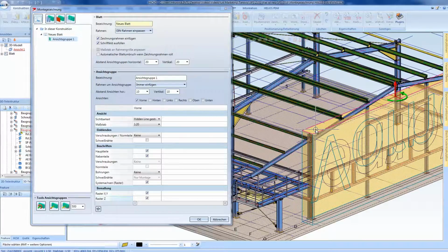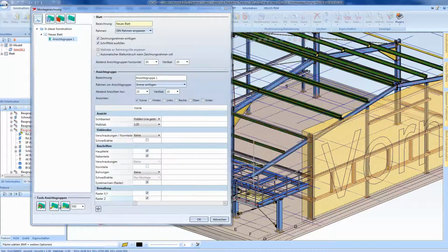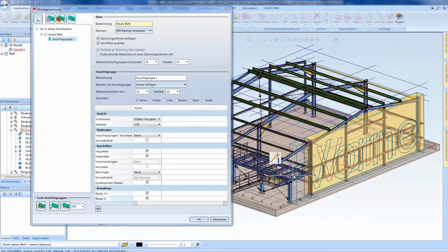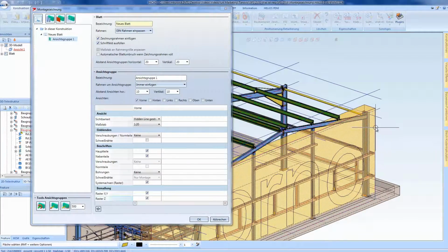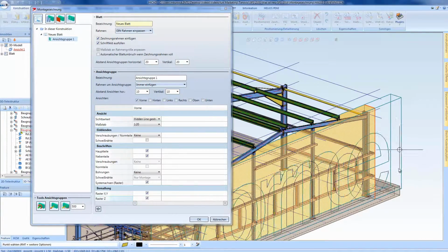We can use these tools here. We can, for example, rotate the box, and depending on the selected facet we will get a preview showing the rotation direction. In this example, the selection is made in the front, the whole thing is rotated 180 degrees, and then the dimensions of the box are adjusted. Here, too, we select this facet, a dynamic preview now appears, and drag it to this point.